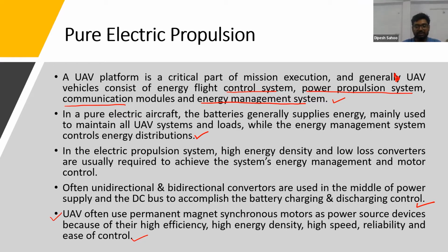And the rotor is either a coil winding with a soft iron core, or it runs on magnetic induction like an induction motor, or we have a permanent magnet, or we can have a switched reluctance motor. But in our drones, generally we use PMSM motors, permanent magnet synchronous motors, since the rotor is already magnetized. Hence, we don't have to use additional energy to magnetize it.